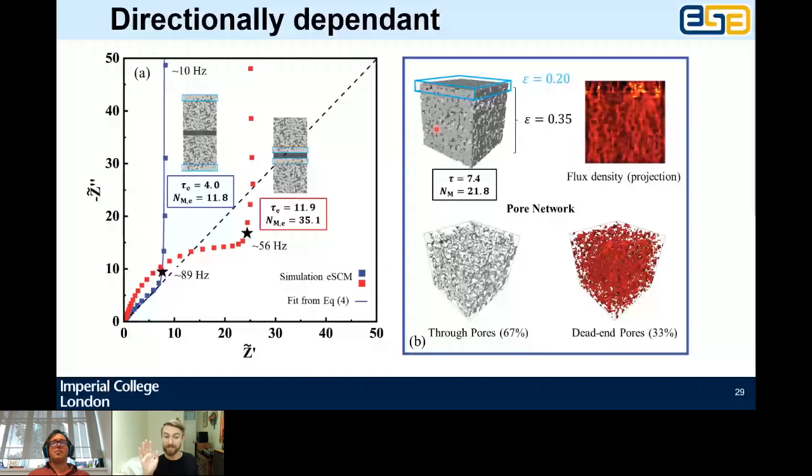Crucially, the conventional tortuosity factor doesn't know whether you're going from top to bottom or from bottom to top with transport. It is agnostic to this. It can do measurements in different of the 3 Cartesian directions, but it cannot differentiate between the positive x direction and the negative x direction. So whether the dense layer is at the top or the bottom cannot be measured with the conventional tortuosity factor. But it can be measured with our new metric, this electrode tortuosity factor that we have proposed.